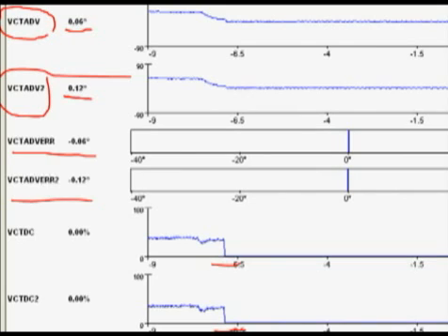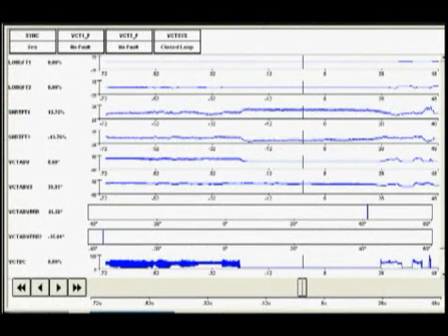The blue bars are at 0 degrees. The VCT duty cycle, the duty cycle for the solenoids, is at 0, meaning that the PCM is trying to advance the cams, and it is being done. Well, now let's let the car run for a while at 2,500 RPM.